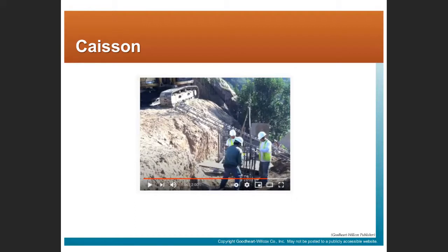Again, if you've been to something at the Auditorium Theater and you walk around in there, it's sometimes a little unnerving because the floor will slope up and down depending on where you are in the building. You may or may not notice it, but it's because the Auditorium Theater's exterior masonry walls have a lot more weight than some of the interior columns. So in a floating raft foundation, those settle a lot more than the other stuff.